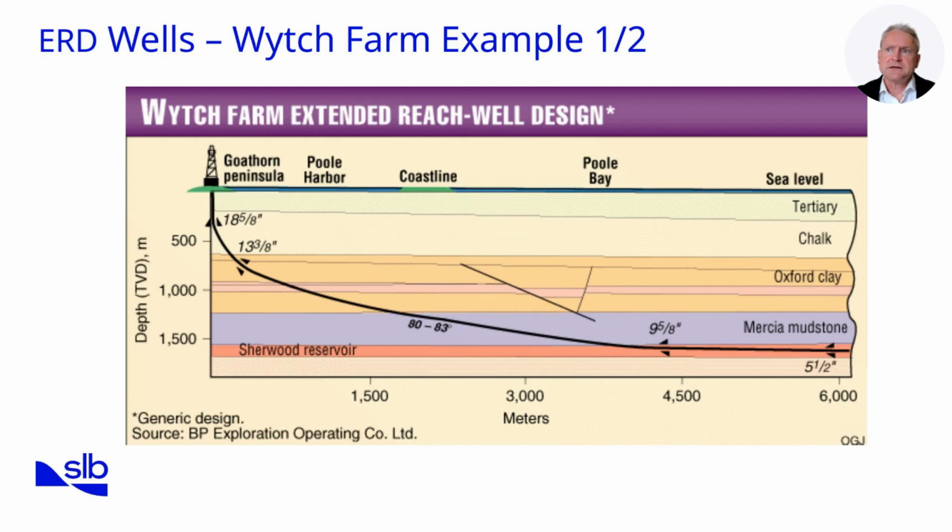The project pushed technical boundaries, with wells reaching measured depths well over 30,000 feet and horizontal displacements of more than 6 kilometres. Managing torque, drag and hole cleaning at those lengths required significant innovation in well design and drilling practices. The Wytch Farm project demonstrated the practicality of ERD not just for record setting, but for economic and environmental reasons. It remains a benchmark for ERD field development worldwide. On the next slide, we'll look at a second example from Wytch Farm that further highlights the benefits of this approach.